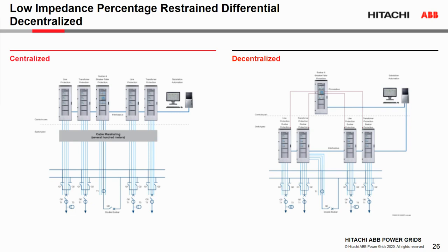Decentralized means you actually have a bay unit in the field. Each bay unit handles only one three-phase CT circuit, so you connect directly in the field, and between those bay units, you can have 20, 30 bay units depending on the implementation set by the manufacturer.